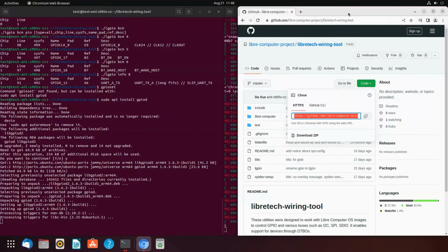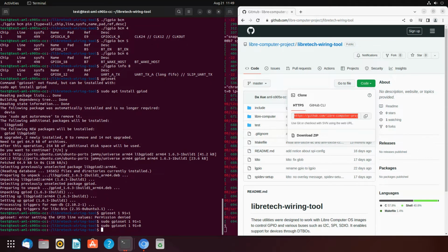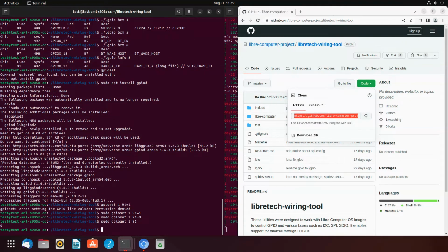The modern method of accessing and controlling the Linux GPIO interface through user space is via the libgpiod library. This library provides more advanced control of the GPIO features such as biases, drives, and modes, along with reading and setting the GPIO lines. You can read GPIOs via gpioget and set GPIOs via gpioset from the gpiod package. To install, type in apt-get install gpiod.